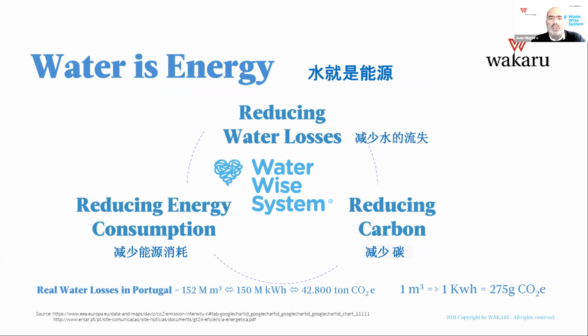And as I was saying, water is energy. So if you reduce water losses, you reduce the need for water, we will also be reducing the energy consumption and thus reducing carbon. Just for having some more insight on this, using information from what happened in 2019 regarding real water losses in Portugal, we had about 150 million cubic meters of real water losses, corresponding to about 150 million kilowatt hours of energy consumption, equivalent to about 43,000 tons of carbon emissions.